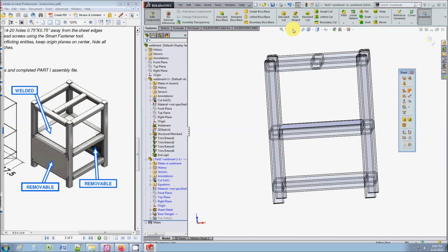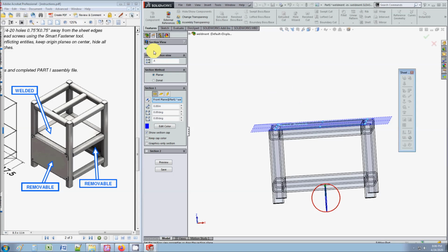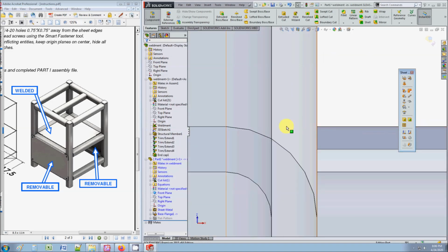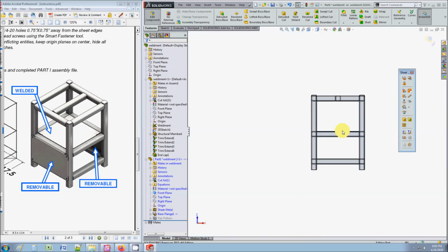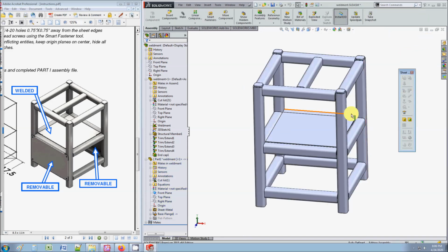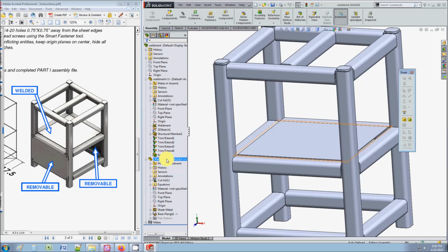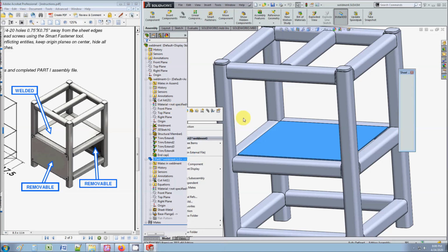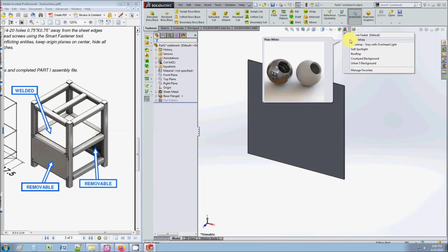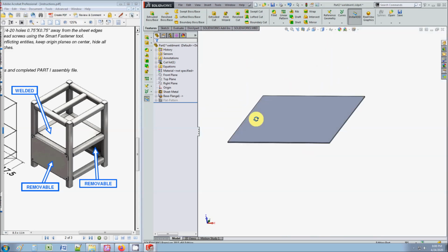So let's see, here's our panel, but I'm still not sure if I extrude in the correct direction. So I'm just gonna move. Okay, as you can see, this is flush, which is what I wanted. So my extrusion was in the correct direction. And there's the panel. Okay, so what I'm gonna do now is right click open part. And again, I just like working in this environment. It just makes it easier. So this is a welded panel.